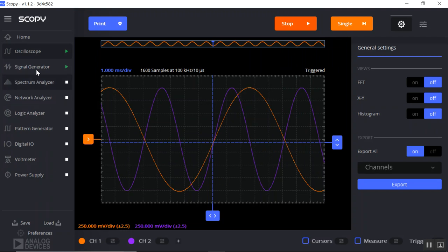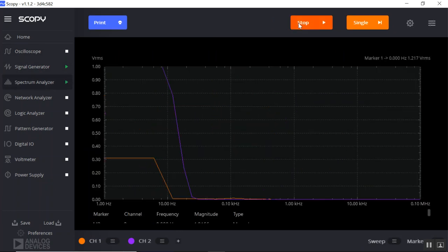So let's look at the spectrum analyzer. So this, you can tell, I can measure this and see what the frequency is and kind of by eye find the amplitude. But the spectrum analyzer does this automatically. So we had a 100 Hertz wave and we had a 200 Hertz wave, and this magnitude is indicating that's what we have. Now it doesn't tell you the phase, but it is telling you that there is a sine wave at this frequency and a sine wave at that frequency.